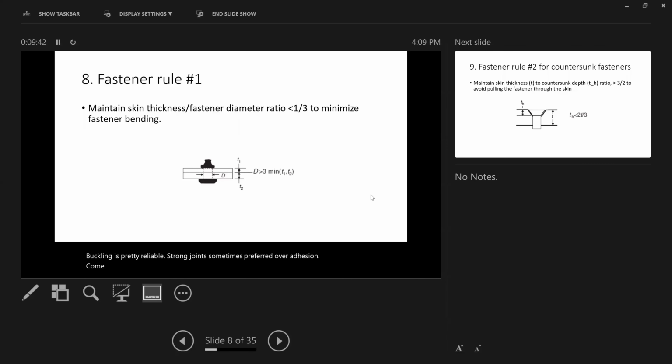One sidetrack: let me talk about corrosion issues. You basically do not want to have aluminum in contact with graphite material directly, for the purpose of corrosion resistance. There is a phenomenon called galvanic corrosion. How many people have heard of galvanic corrosion between aluminum and graphite? Materials have different levels of nobleness. This is one way to capture the corrosion potential of a material.